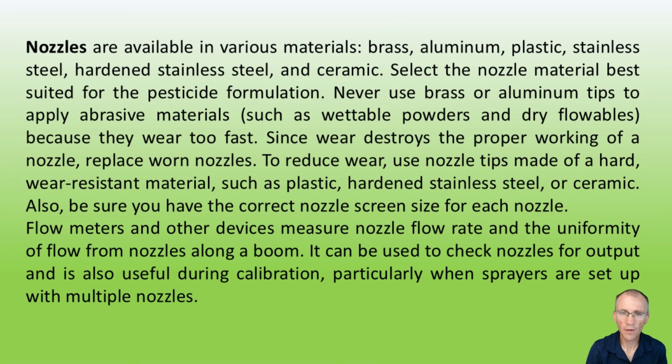Nozzles are available in various materials: brass, aluminum, plastic, stainless steel, hardened stainless steel, and ceramic. Select the nozzle material best suited for the pesticide formulation. Never use brass or aluminum tips to apply abrasive materials such as wettable powders and dry flowables because they wear too fast.